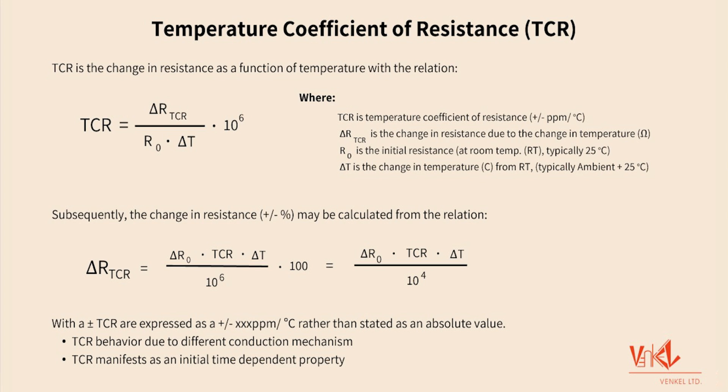This behavior is particularly critical in precision applications where maintaining consistent resistance values is essential. Understanding TCR is vital when designing circuits exposed to varying temperatures. By selecting resistors with an appropriate TCR value, engineers can mitigate temperature-induced drift and ensure reliable performance across operating conditions.